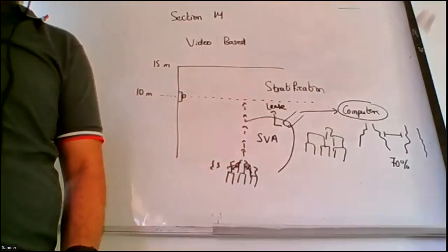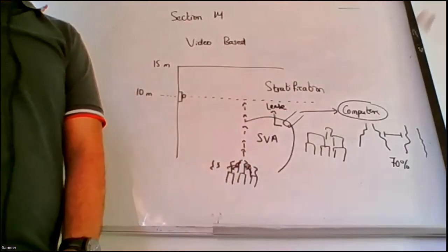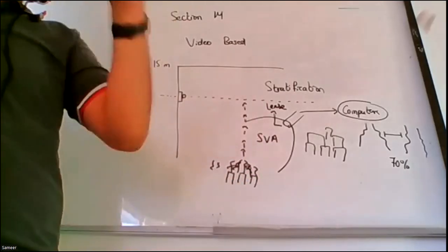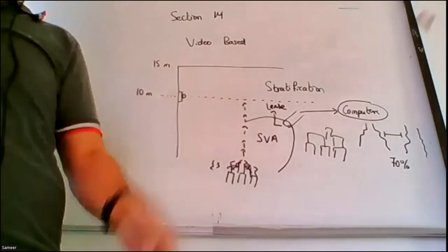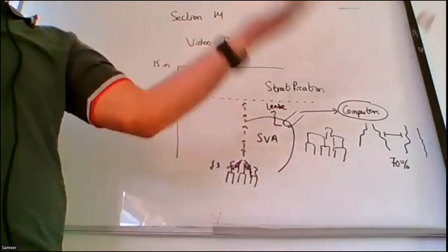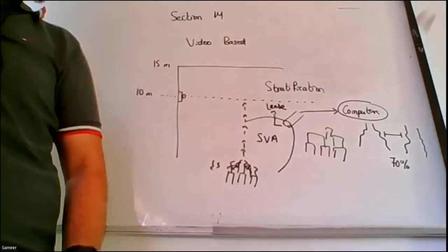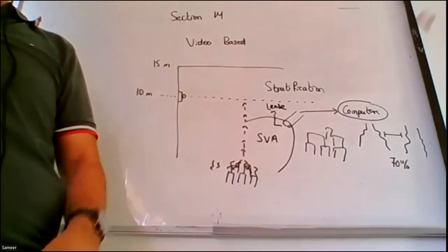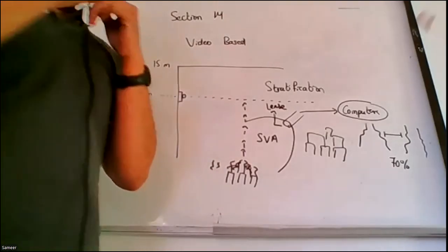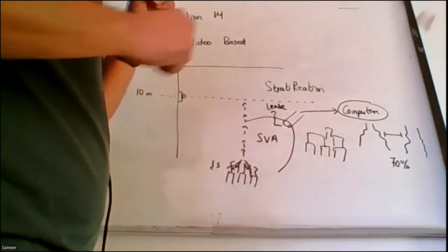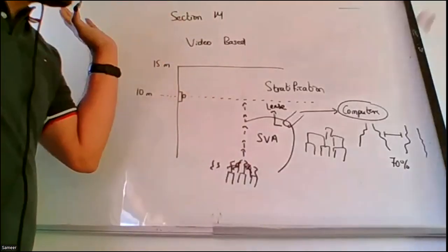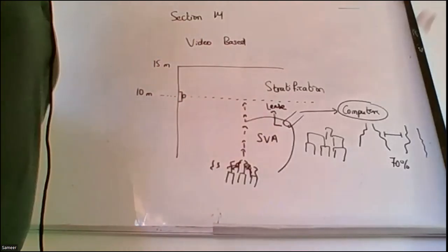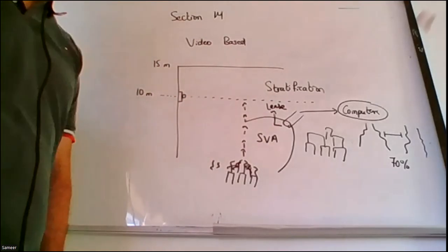Video-based detectors are used in these occupancies to avoid stratification, because the ceiling height is very high. Actually all detectors should be installed to avoid stratification, but in warehouses, ceiling-based detectors will always have stratification. Beam detectors will always have stratification. So for that purpose, these detectors are installed so that we can avoid stratification in warehouses and commodity storage areas.